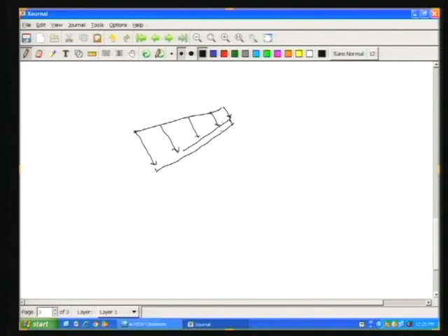Of course, it is not increasing linearly with y, but with z, and that is why you have the sin theta component. But as you can see, the intensity of the normal force is increasing as you go down. So, you expect that y_cp will be below y_c, and y_c is 0. So, the expression which you have got agrees with your intuition.